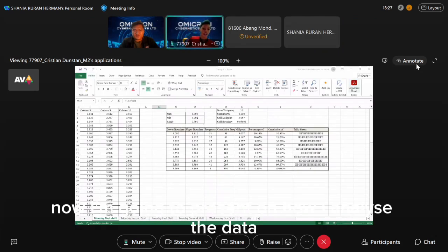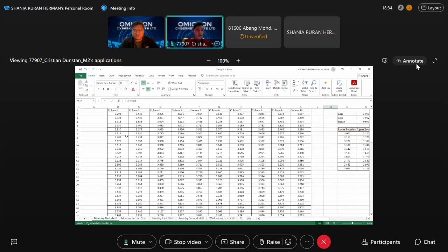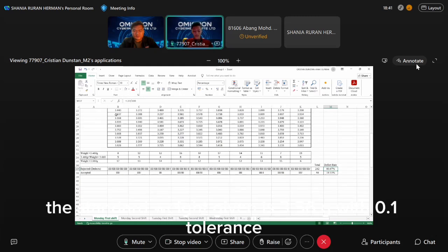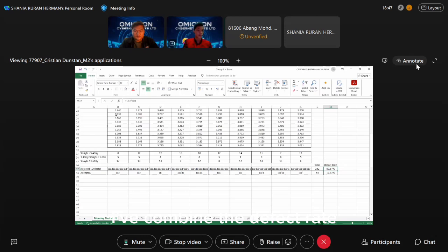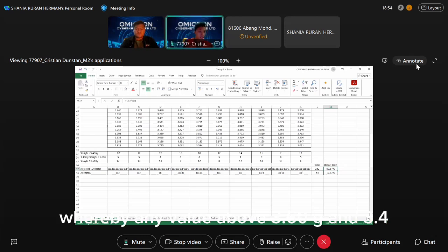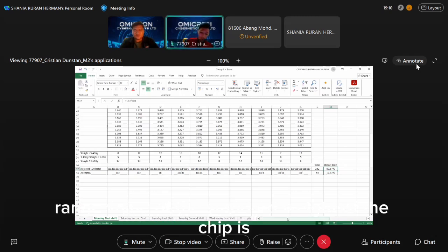Thank you, Mr. Aris. Now I'm going to present on how I analyze the data. For example, on the Monday first shift, I selected the 300 range of data, and from there, the standard weight given is 3.56 gram with 0.1 tolerance. I've combined the defect rate, whereby any value above 3.660 gram and below 3.460 gram will be counted as defect. For example, on the Monday first shift, the defect rate is about 80.67%, while the expected range value of the standard weight of the chip is 19.33%.